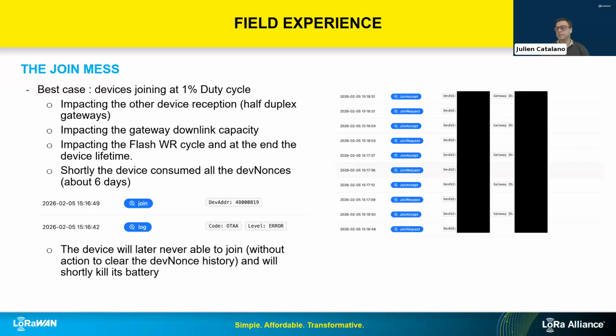because the LNS will basically filter the traffic based on the DevAddr. So if you use a DevAddr range from someone else, basically you can create extra processing on this other network's LNS. So that's not fair. Yeah, exactly. That's the same as for the EUI-64. You should use your own block of numbers. Otherwise, it's a device which is polluting, in the sense that it's not recognized by the network it's supposed to join.